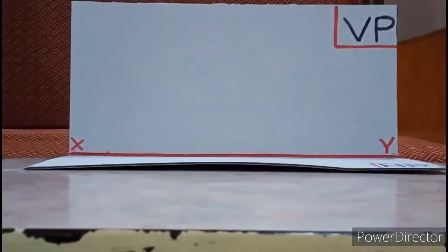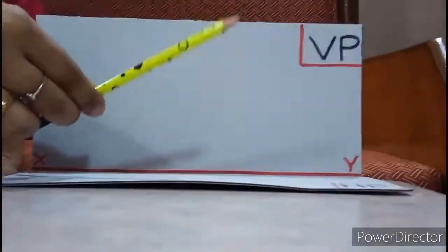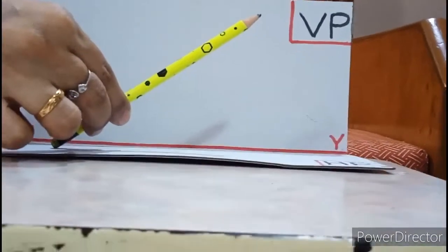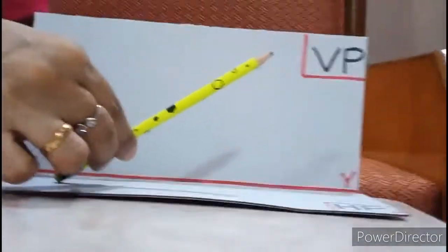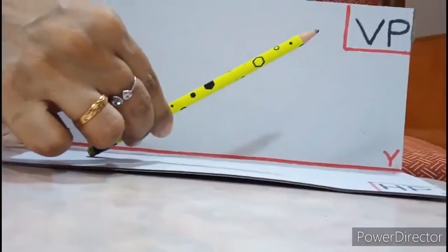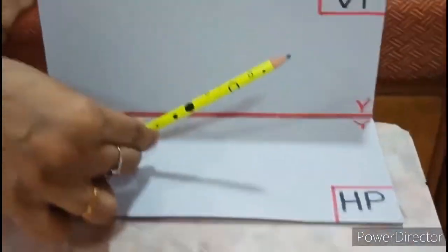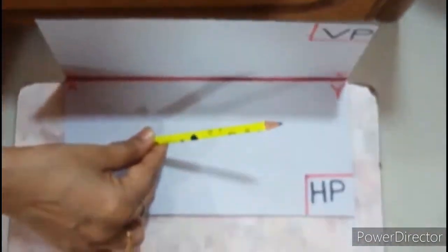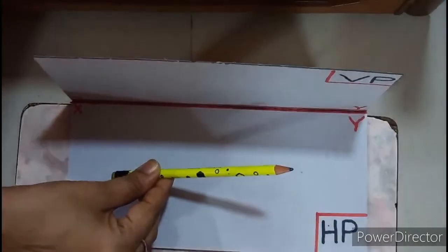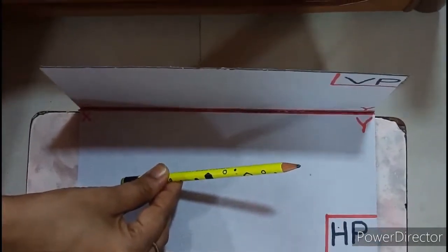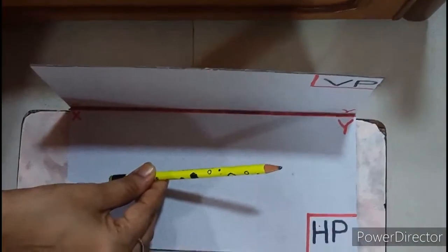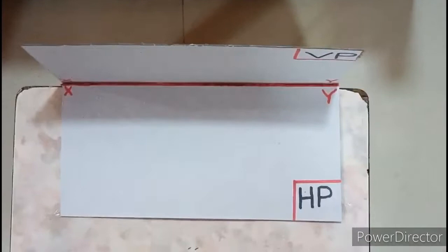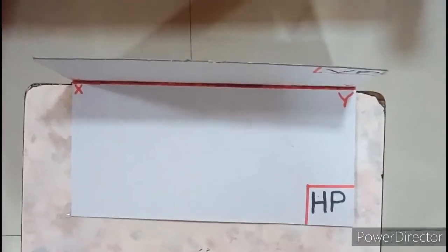Now let me place a line which is inclined with HP, as you can see here. The line is inclined with HP by angle theta. This theta angle, the angle made by this line with HP, can be seen from the front view. And if I slowly move above and try to visualize from the top view, that angle cannot be recognized. It is seen as a straight line only. You cannot see that angle. So that is how it is. Now similarly, if you look perfectly from the top view, you can see VP as a line, isn't it?